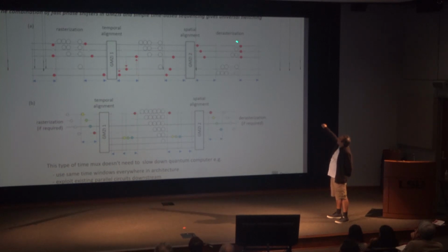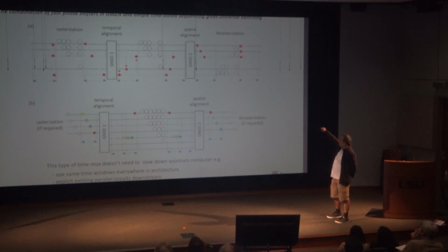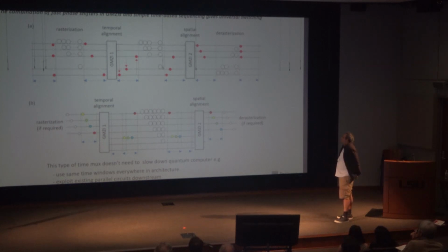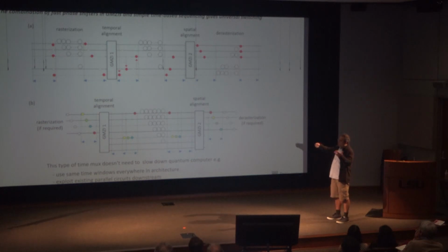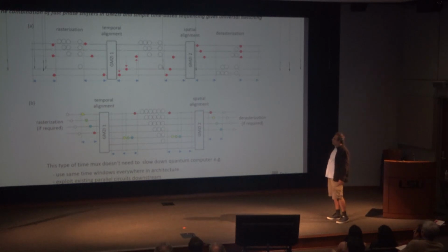So in a sense, they're nicely organized into space-time bins, lined up, similar to the way they came in. So this is a very nice time multiplexing idea. If you imagine a full stack, you're already going to have muxes. So it's very cheap to add staggering of delays and sequencing of operations.